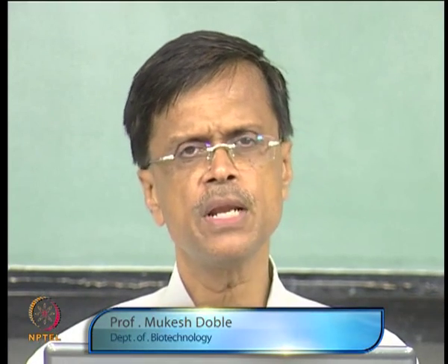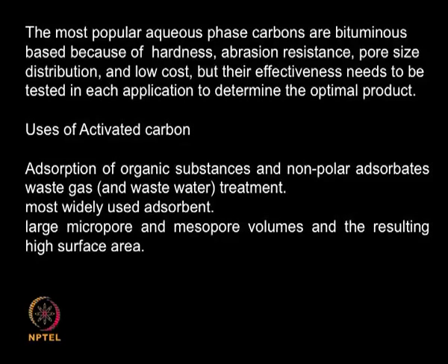So the most popular aqueous phase carbons are bituminous based, because they are very hard, they have very good abrasion resistance, good pore size distribution, low cost, and they can be used for a large number of applications like organic substances, non-polar adsorbates, waste gas treatments as an adsorbent and so on. That is why it has very good applications in several manufacturing processes. Okay.